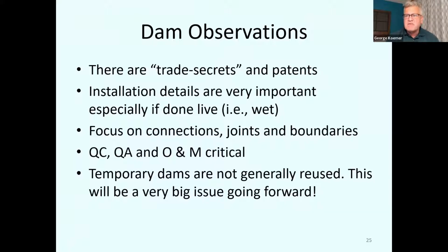One of the big things we're finding out is geomembranes on the face of the dam, particularly in cold weather, are seeing bombardment from ice movement as well as debris flows. So it has to be puncture resistant. There are active systems available for this, like bubblers. In addition to that, there are screens and nets which are placed around the water line to get away from the debris problems.